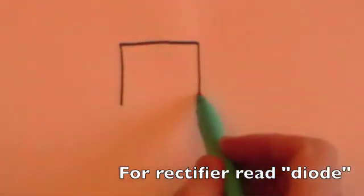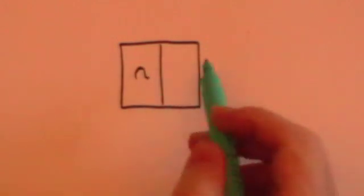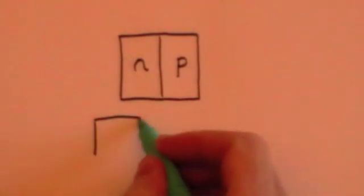In the video on rectifiers and capacitors, I introduced you to the idea of a rectifier, and I said that it was made up of two materials, N-type and P-type material. Now let's just remind you what they are. They are both made of silicon. Silicon is a semiconductor, which means that it does have some free electrons, but nowhere near as many as a conductor, a metal, has. But neither is it an insulator, but you won't get very much of a current flowing through a semiconductor because it's halfway between a conductor and an insulator.